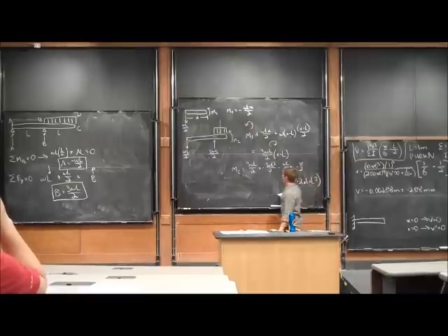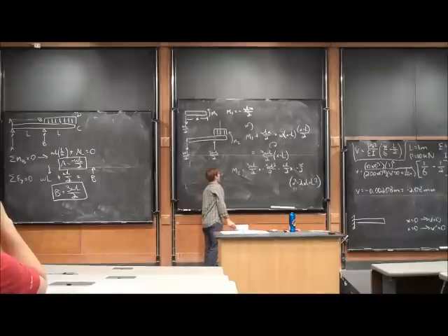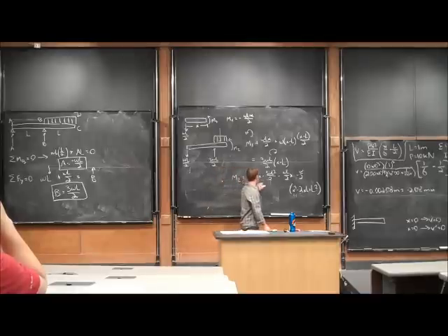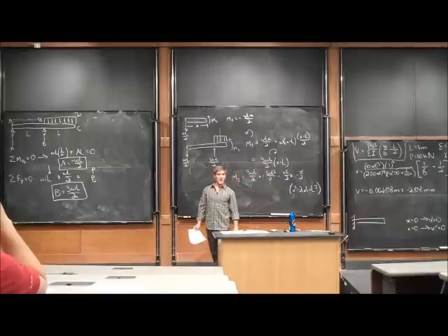So that's a much more complex moment equation that we're going to have to integrate now and apply boundary conditions to. You always want to multiply things out as best you can, because when you integrate it, you're just running polynomials, and it makes it a lot easier if you can look at each term individually.